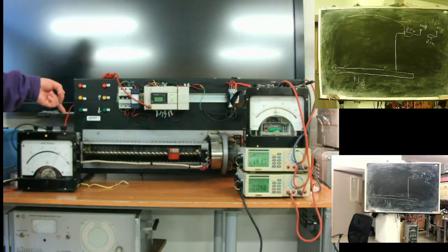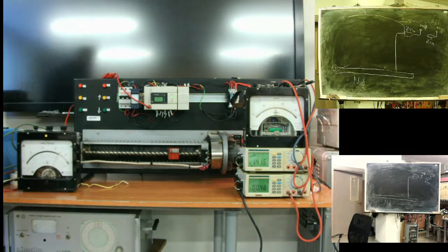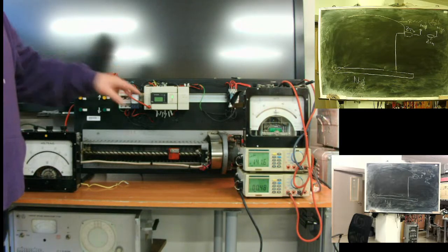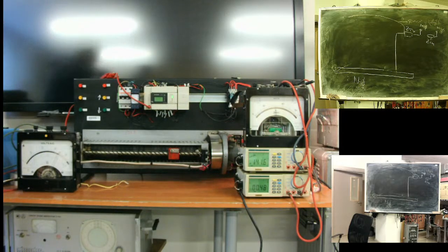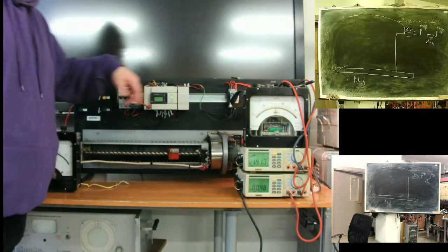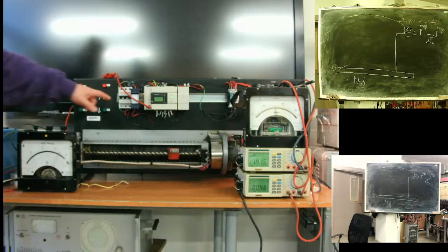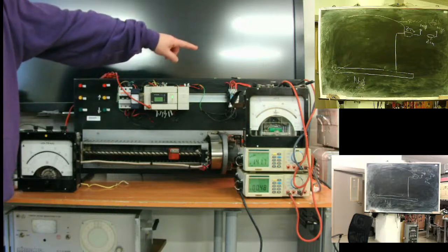It's a rheostat. Usual rheostat, but with drive. And it has a control system. Two channels. This model converts analog values into digital. It's an analog to digital converter. One channel is powered from this small rheostat, it's a set point. And another channel with this converter receives a load voltage. So the rheostat is loaded with 3 volts.